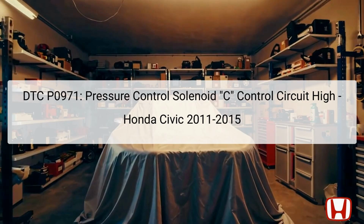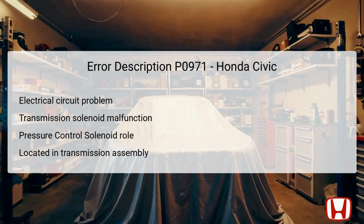Before executing any diagnostic procedures, it's crucial to consult the general troubleshooting information pertinent to Honda vehicles to establish foundational steps needed for effective troubleshooting. The DTC P0971 error relates to an electrical circuit malfunction affecting the Pressure Control Solenoid C in the Honda Civic. This solenoid plays a crucial role in controlling the hydraulic pressure necessary for the CVT to operate efficiently.